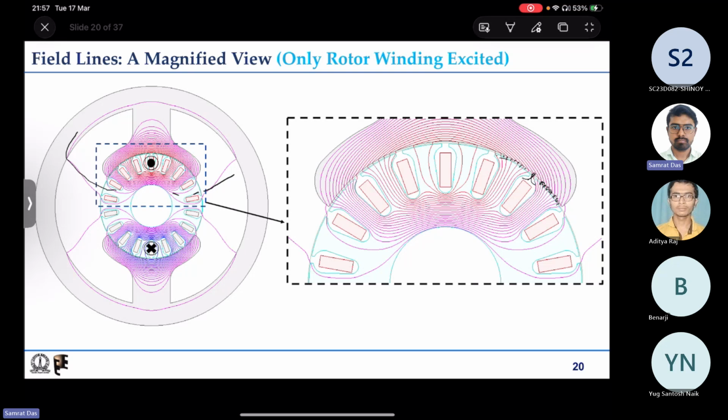So if I plot the variation of Lg along theta, then wherever there is overlap, there it will be very small, say like G, and wherever I have the slot openings, then there will be some increase. How to express that increase? That is difficult, but you can have a feeling that there will be an increase, an effective increase of the length of flux line through the air gap.